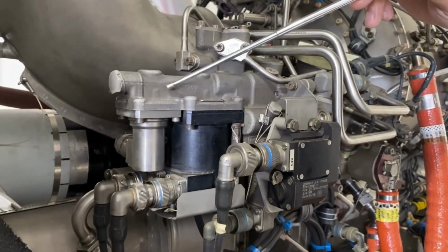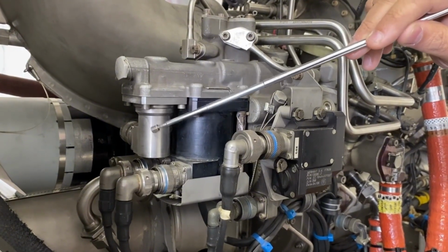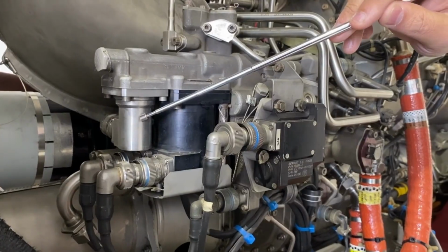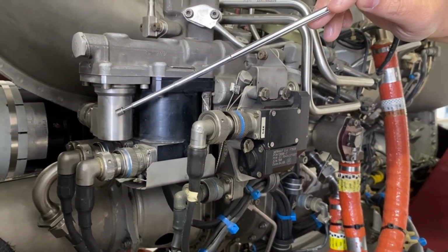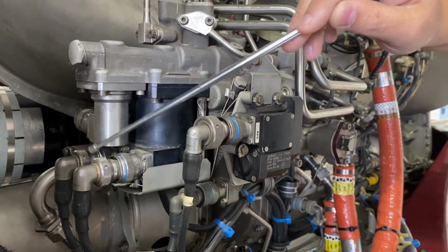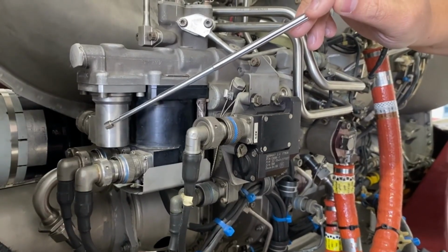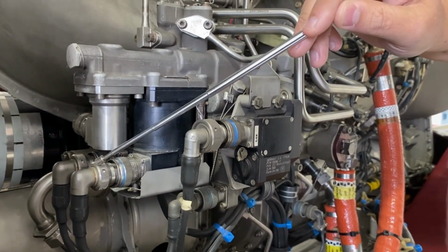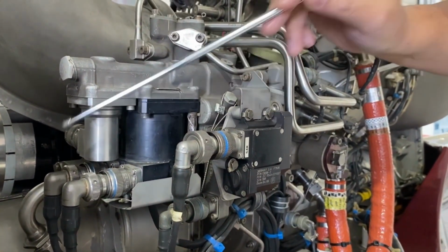When the needle is commanded to move one way or the other, this here is a resolver transmitter, which sends a feedback signal to the FADEC, telling it the position of the needle, whether the commanded position matches the current position. If one FADEC channel fails, the FADEC operates with the other. In this Ariel 2B1 engine, channel A always operates, and in case of failure, channel B takes over. But in the Ariel 2 Delta, they alternate from flight to flight.